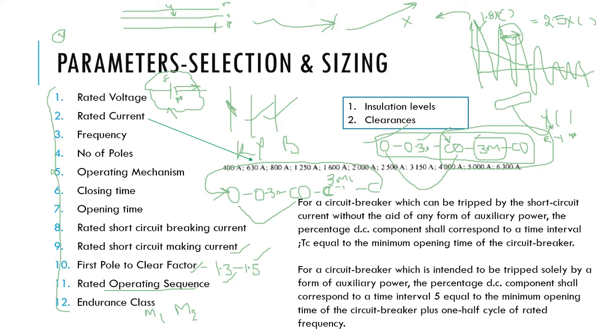So additionally, on top of 25 kA, I require one more 10 kA for the DC component to break or to make, whatever it may be. In normal substations, these breakers will not experience this DC component. Only the generator breakers which are nearer to the generators will experience it. Okay, that is fine. Thank you.